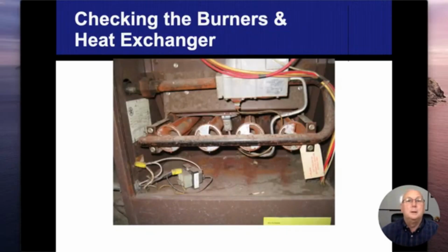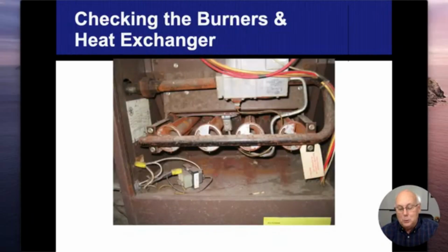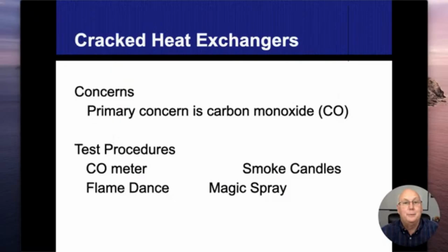So go from there. Another natural draft furnace. Everything's open on the inside of this thing. Yeah, I got nothing much more to share. You can see all the rust and corrosion, and same thing going back to this one. You can see how rusty everything is on the inside. These old natural draft ones are just old. They're just in bad shape. I don't know what much more to say. At this point in time, even if it isn't running safe, I still want my client preparing for a new furnace.